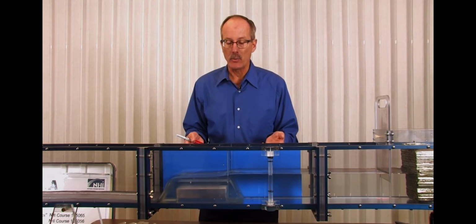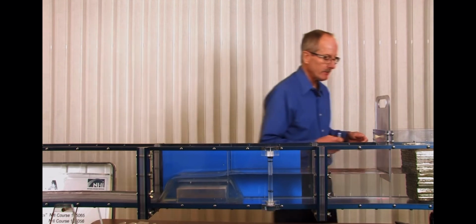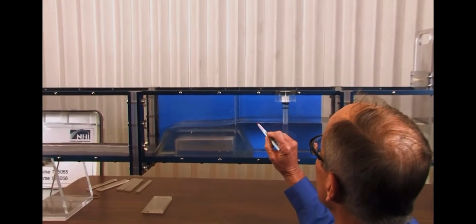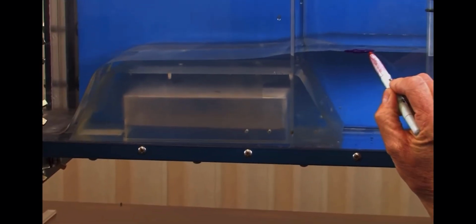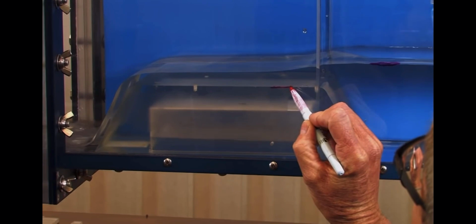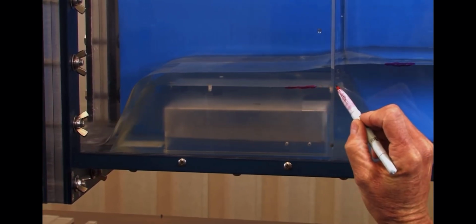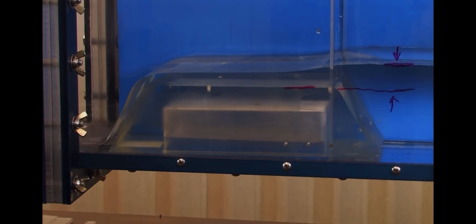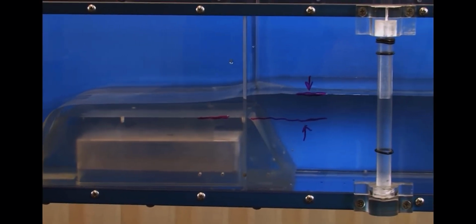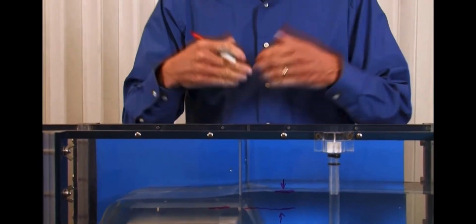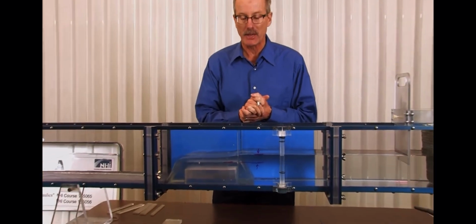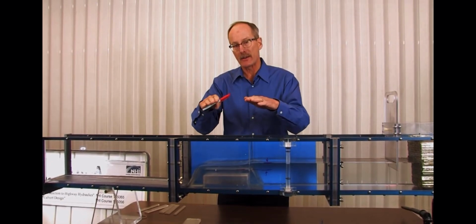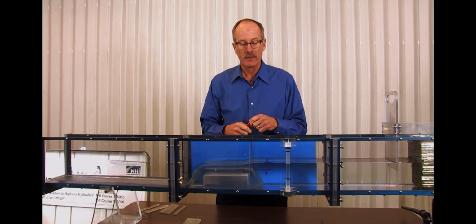The head acting on the weir is the difference between the upstream water surface and the height of the weir crest. So as flowing at the moment, the H value is about an inch. It's not very much. And it's measured a little bit upstream of the weir crest to get away from the drawdown as we go over the top of the weir.